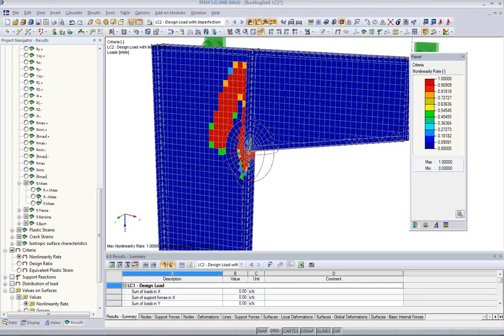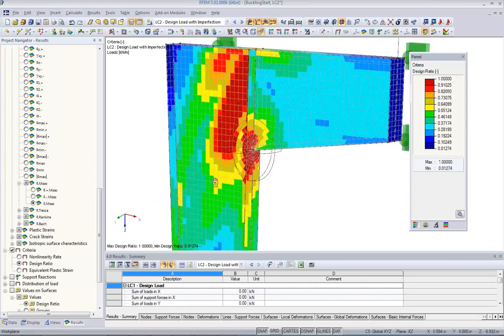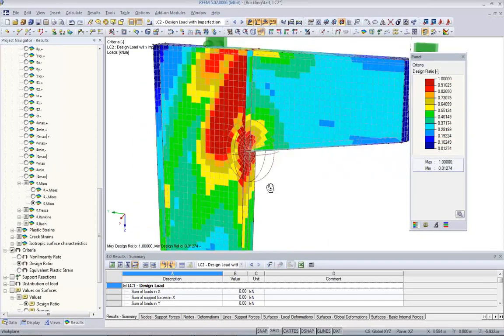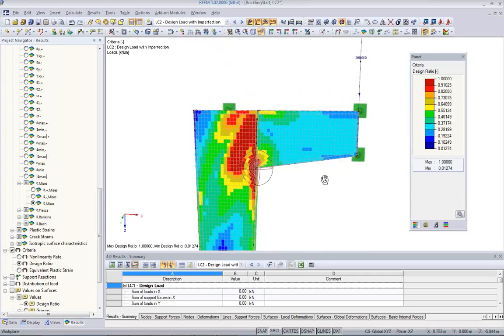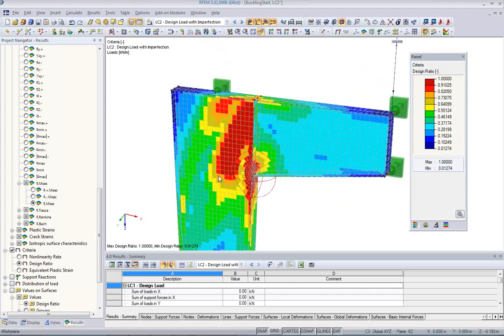Also, we should again check the stresses, and they are now also higher and almost above the limit that we allow. And this here is a very slender structure, so I don't know if we should really build it in reality and do some more stiffening. But the principle like this is good for showing how we do such design, and now, based on this, you can decide whether you introduce more stiffness, whether you change web thickness, and so on.